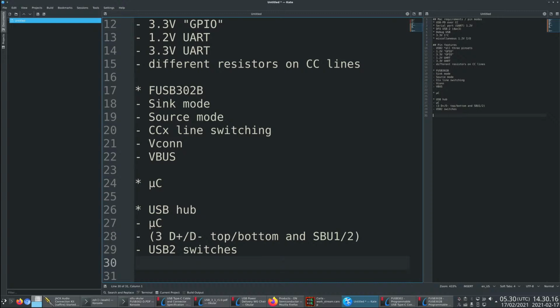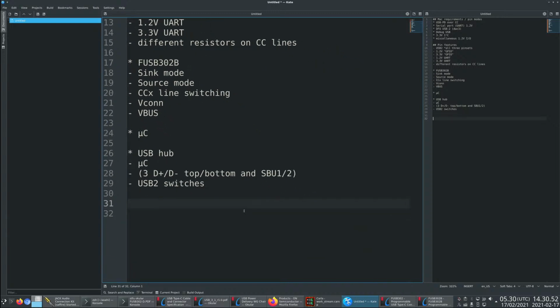So yeah, Rod is talking about the VBUS pin. So when we're talking to the Macs in serial port mode, we need to be a source. So we need to be basically a USB host, which means we need to supply power to the Mac, even though it's not going to actually use that power if it's a Mac Mini. And that means we need to provide 5 volts. Now, if it's a Mac Mini, the power required is basically nothing. So for a Mac Mini, we can just pass through the 5 volts from the host, and that means we need a switch. I'm going to make this smaller now.